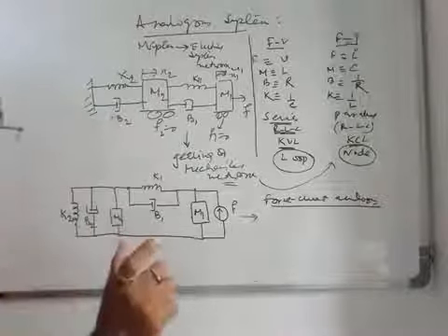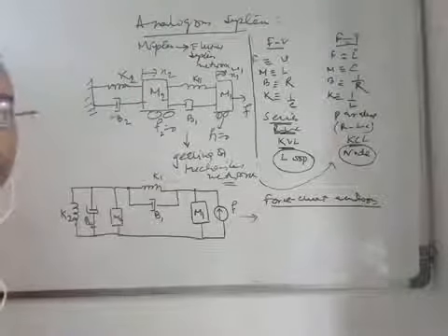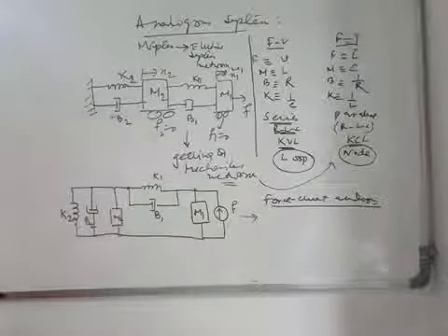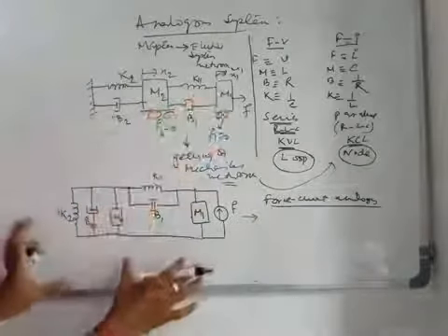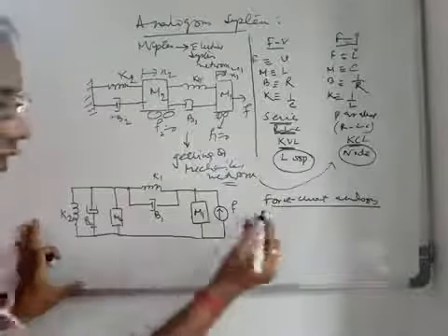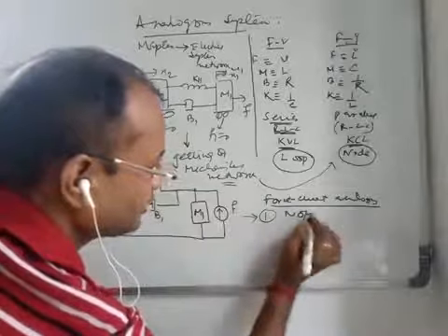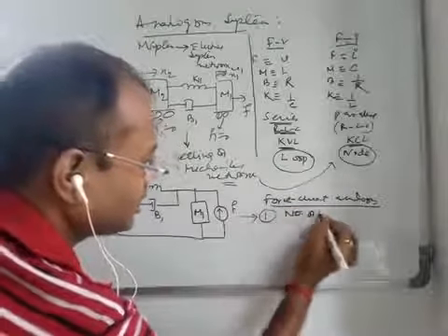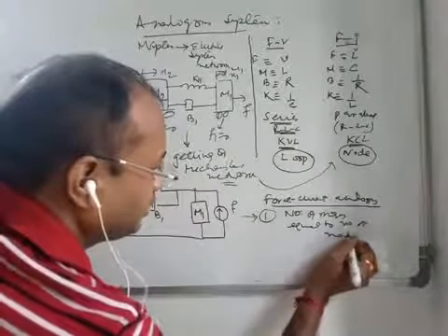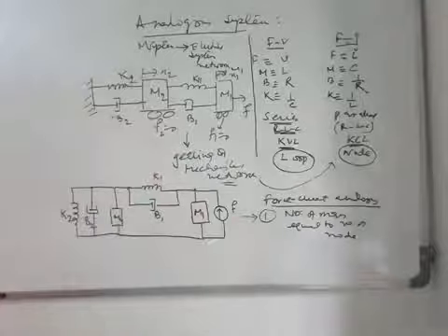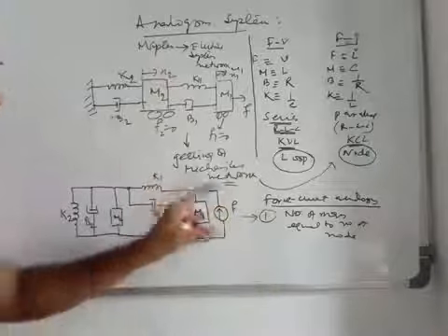The number of nodes in the electrical network corresponding to the mechanical network will be equal to the number of masses present, right? So from this structure, the easier way to remember is to just make a mechanical structure like this, or the mechanical network is like that. So number one is that the number of masses is equal to the number of nodes. Okay, so this is the basic and foremost criterion to draw any force current analogy.